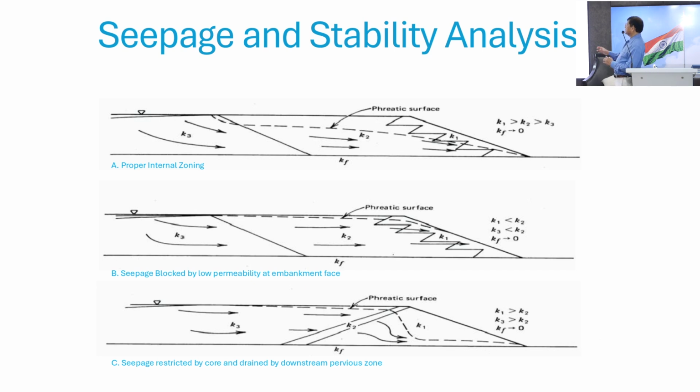Again we see slime and sand in the upstream. Even though it is sand, you see the pore pressure or the phreatic surface is higher. If you go to a downstream or a central line, you can bring it down. So that is the usefulness of the central line and downstream versus the upstream. In upstream we always see a higher phreatic surface and higher pore pressure.